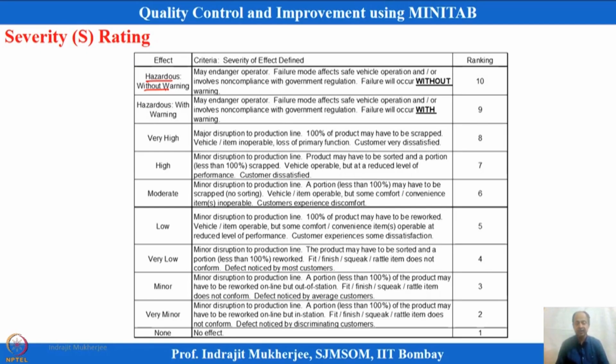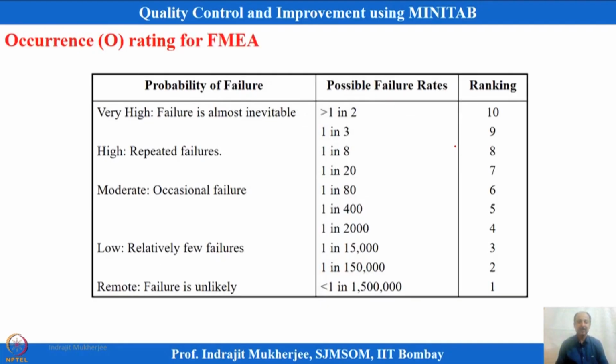So, it will happen immediately, like brake failures or something like that; it is hazardous like that. So, the rating will be 10. So, the severity rating will be 10 like that. Okay. And the severity rating will not change for a potential failure mode. So, that is the severity rating.